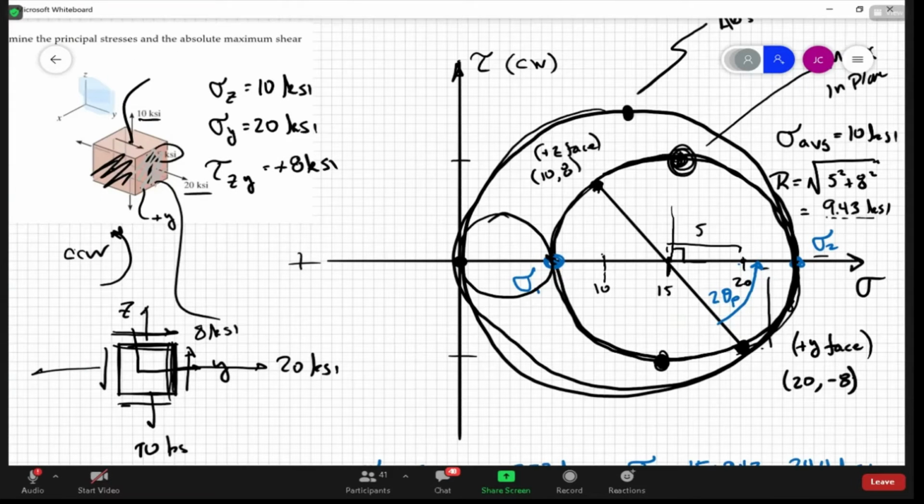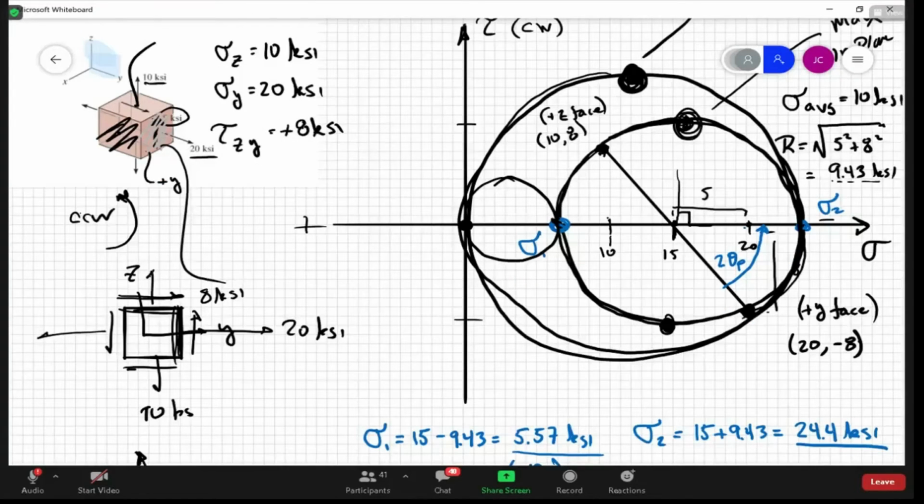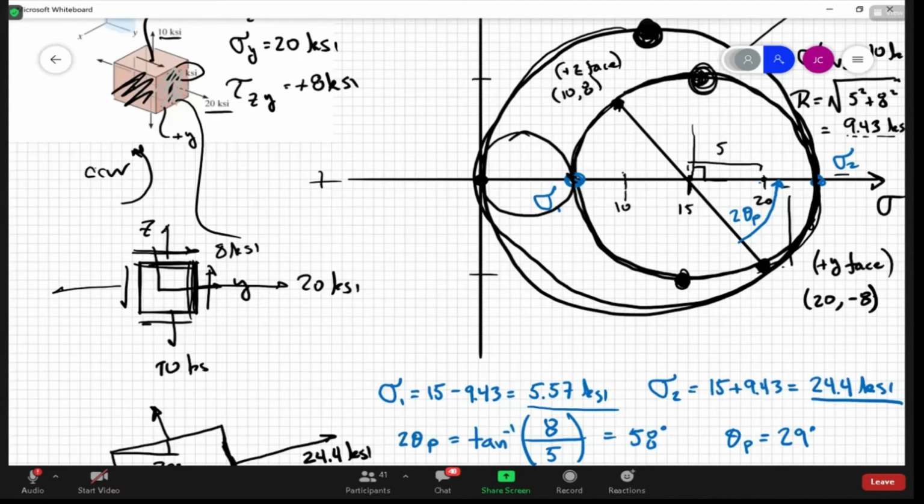But suffice to say, what that basically means is you have to imagine, when we're going from in plane to principal to max in plane, we're rotating only around the x-axis in this problem. But this particular state here is going to correspond to a rotation that's also rotating away from the x-axis. So it's around some axis of rotation that's not corresponding to the x-axis, okay? So it's hard for me to draw those. Forget about doing the mathematical derivation, but we can still figure it out.